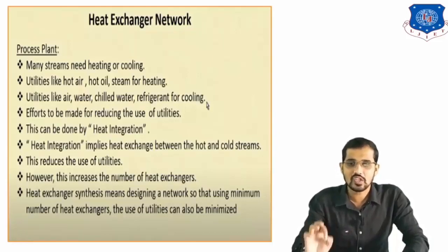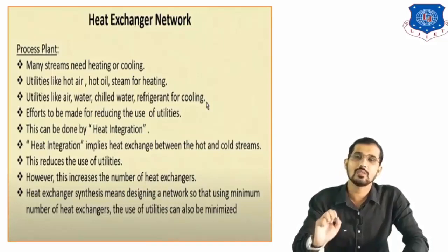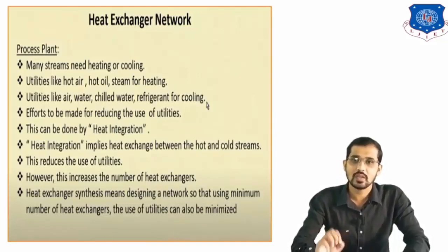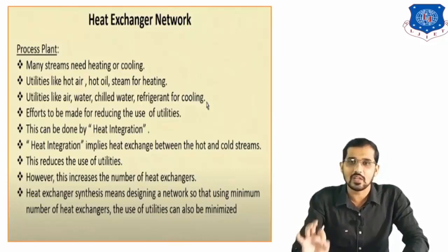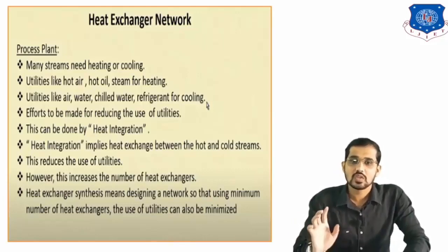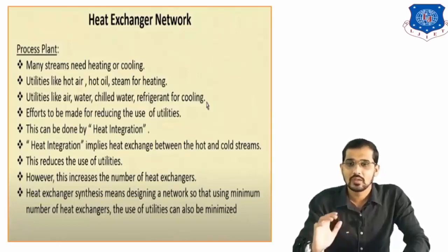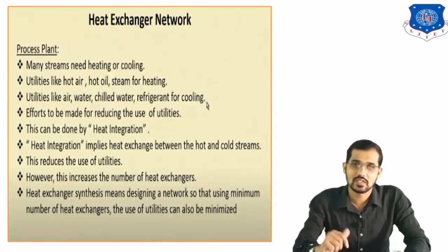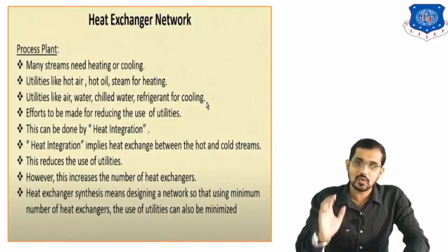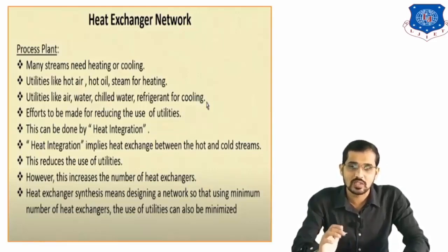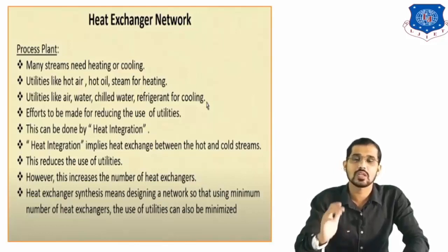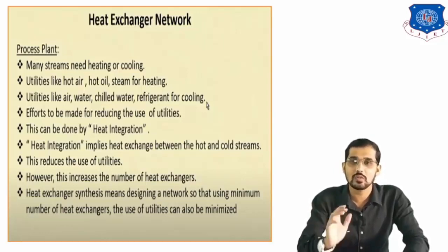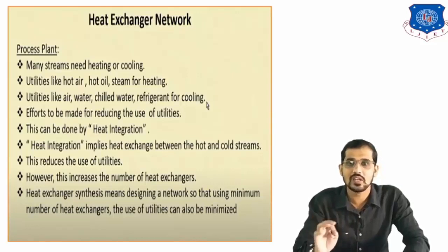After that, heat exchanger synthesis. Now the next concept is heat exchanger synthesis. So what is the meaning of heat exchanger synthesis? You can see on the screen, it means designing a heat exchanger network. We are designing here a heat exchanger network so that using a minimum number of heat exchangers, the usage of the utilities can also be minimized. Whenever you are minimizing the process utilities, those are nothing but external utilities, cold utilities or hot utilities, you are minimizing those utilities by using heat exchangers.